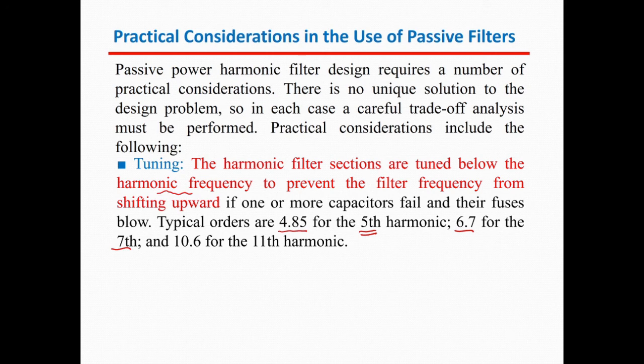it will coincide with the resonance. Okay, we don't like that situation to happen. Of course, if it happens, then the value of the current that passes through the filter will be so huge. Then in that case, of course, that could cause problems to the filter itself and to the capacitor, mainly to the capacitor bank.